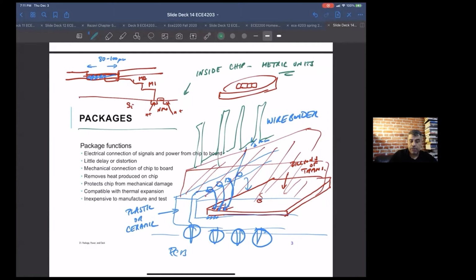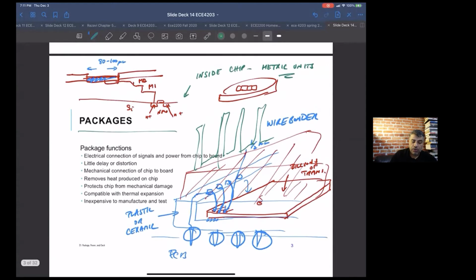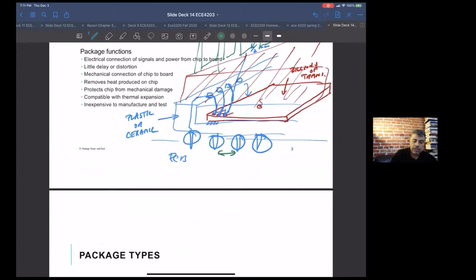the US. For all, I mean, I haven't really worked in any other country outside the US. So, like, if you want to say, oh, what's the distance between these pins or whatever, they're given in inches and this unit that took me a long time to get used to called the mil, which is 1,000th of an inch. So I went through my whole schooling not having heard of mils or anything like that. And, first time I heard it, I thought what they really meant was it was like sort of a misspelling of millimeters or something like that. Totally wrong. Mils is just 1,000th of an inch. So 1 mil is 25.4 micrometers.